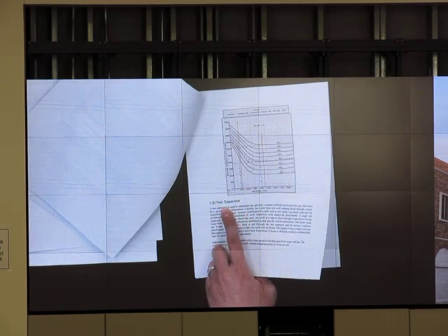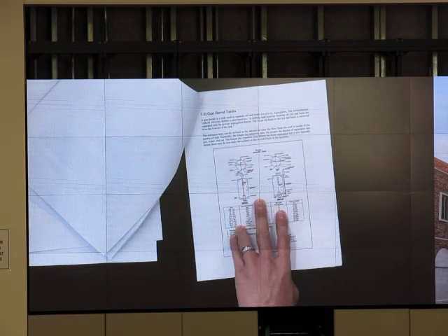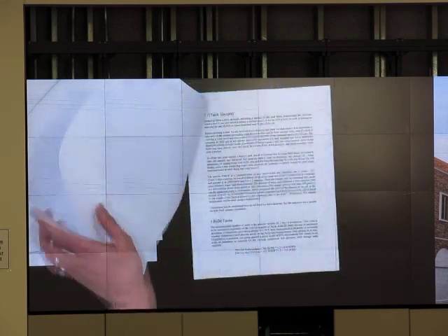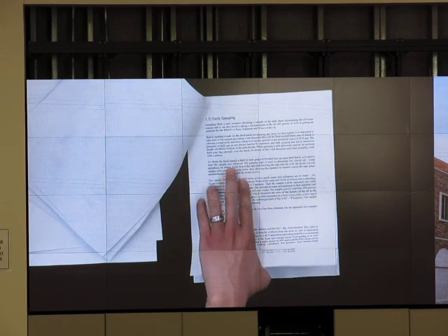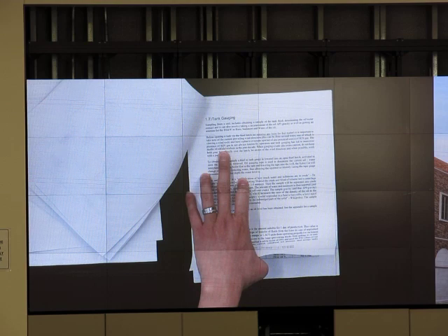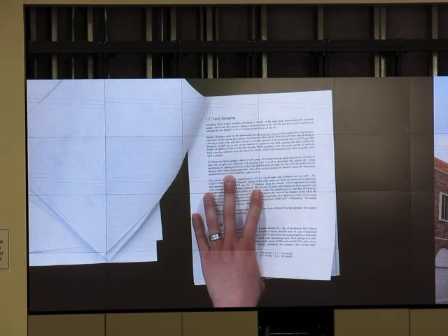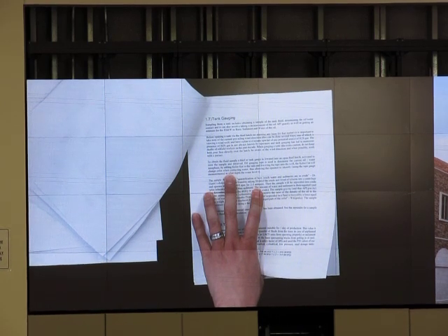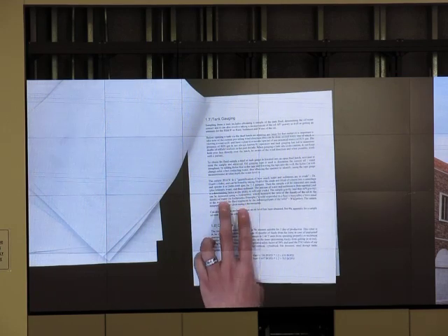Test separator, talk about the test separator, and gun barrel tank, copy the picture and discuss a little bit more. Tank gauging, how do they gauge the tank, how to not die during gauging the tank, okay? I talked about it during the class, right? So it is important enough to put in your report. Even though there's no H2S, people die because they open the tank, okay? Hydrocarbon vapor gets into their lungs and they die.